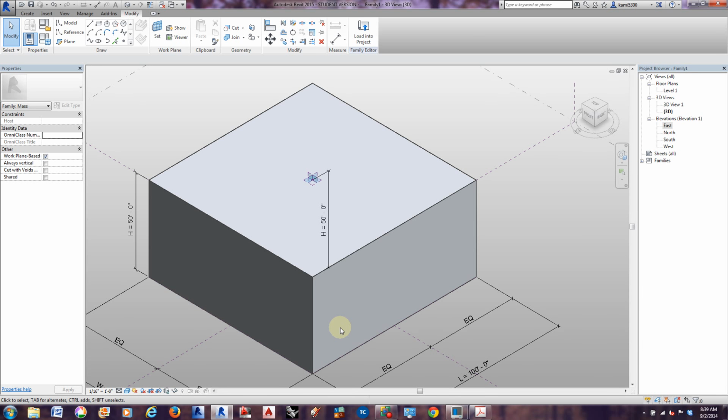So, do you have it placed? Yes. Okay, so you're in the elevation view. We want to select that line, which is the first floor reference plane, and hover over this. You notice it highlights that whole line.